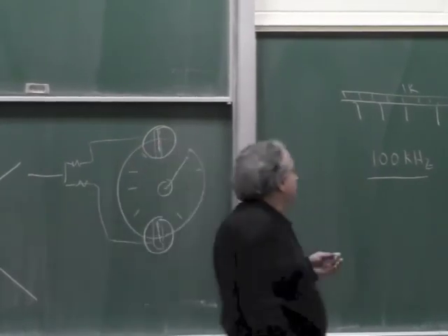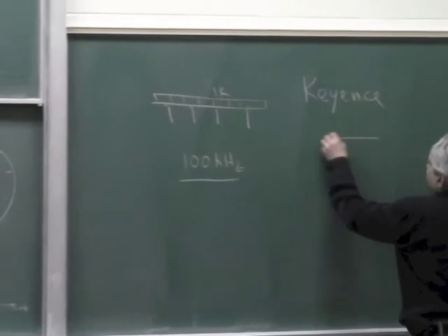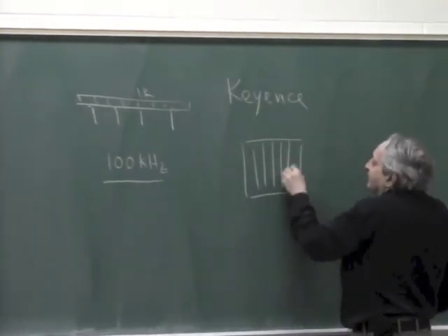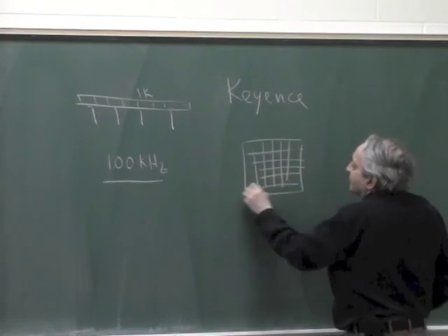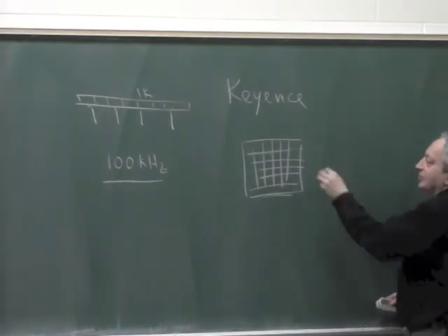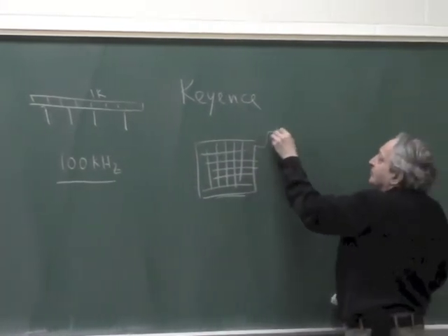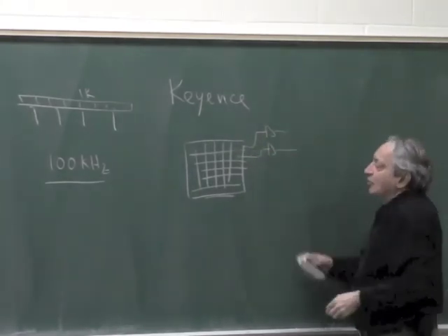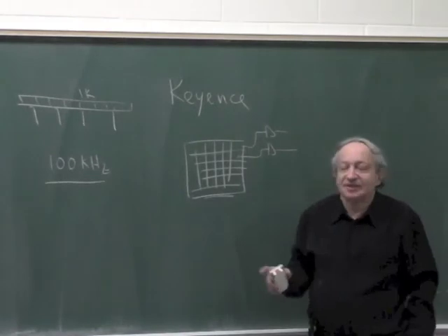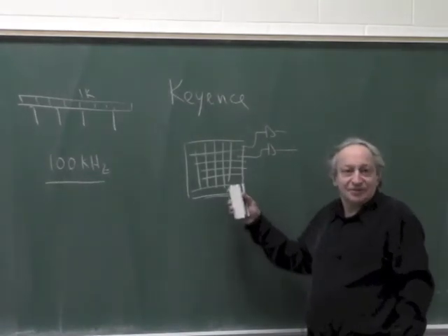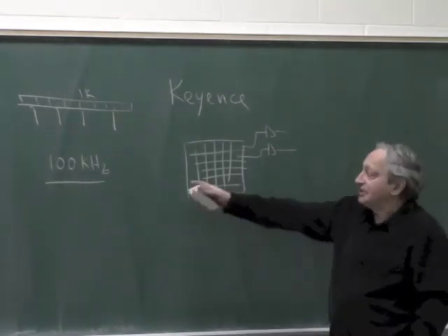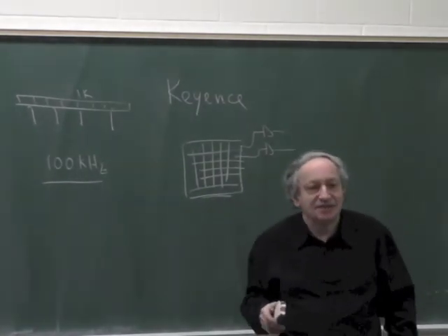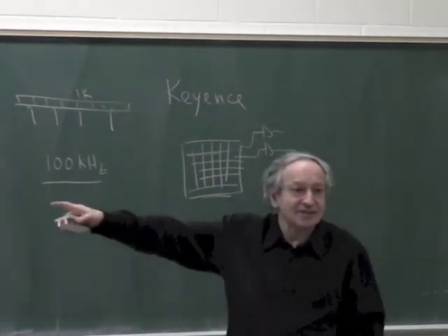Let's say you want to build a custom chip which has 100 by 100 sensors, so it's 10,000 sensors, and you want to bring each one out with its own amplifier. Then this will operate at the same speed as a single detector. So in commercial chips, I would say that's the limit for linear, and maybe 1,000 hertz is the limit for arrays in commercial chips.